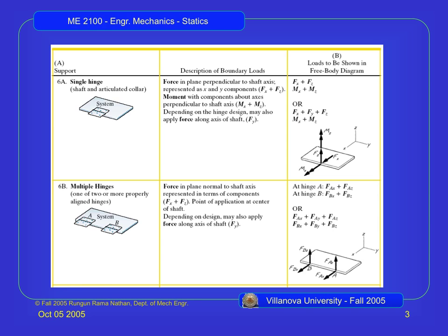So where's it rotating about? Where's the axis of rotation? Yeah, at the bottom, down here. Here's where it rotates about, so double hinge. Now, that rotation is allowed this way, right? So if you were to think about this as the axis, the ruler is the axis of rotation. Is that clear what I'm saying? So you would not put MZ there because it is allowed to rotate. So look at the hinge in the first diagram. You don't see MZ along the hinge, do you?